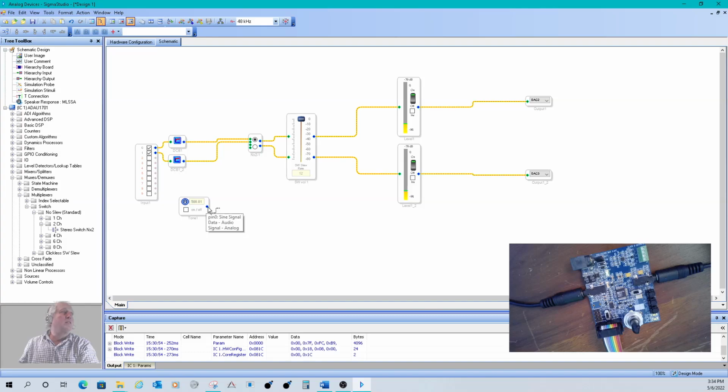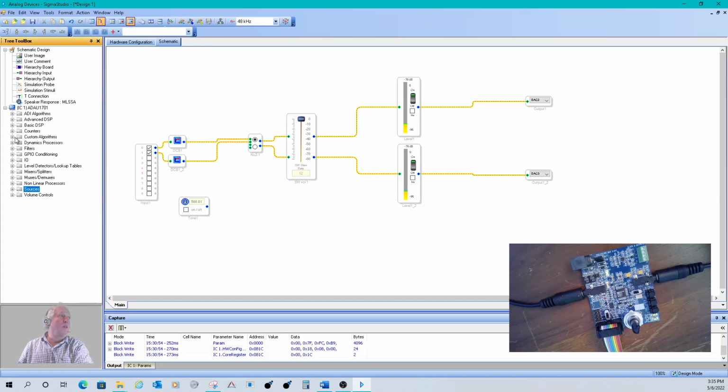Anyhow, so we've got to hook up the oscillator. Well, the oscillator is mono, and we've got stereo here, so we have to deal with this. Well, the easiest way, and nothing stops you from doing this otherwise, we have mixers and splitters. We can go to a splitter, single control, slew or no slew, and get a splitter to split the signal. But that costs MIPS, unless you need to do the volume control for it. Actually I will be, I'll take that back. But I'd still rather do it discretely.